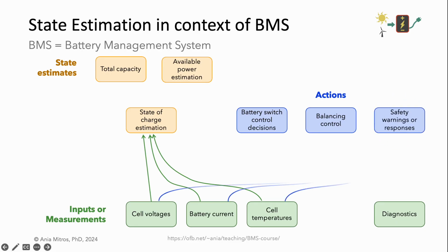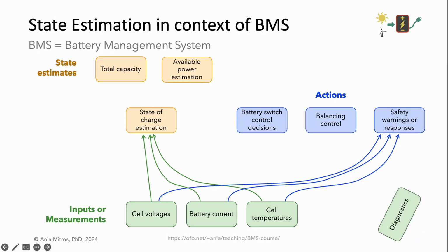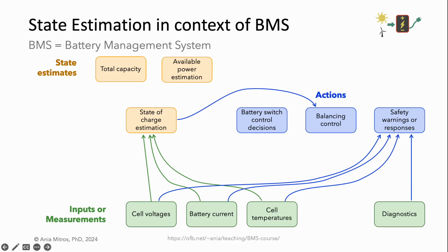But I would argue that for large batteries, such as in electric cars and in home batteries to supplement solar, safety is an equally important and complex topic. The BMS may implement additional diagnostic measurements to support fault detection and safety. Balancing is a small function in terms of current and complexity, yet essential.